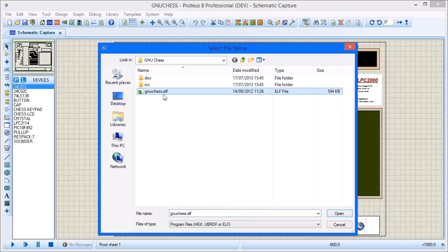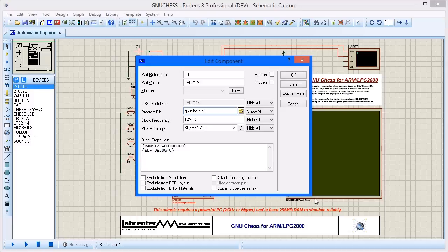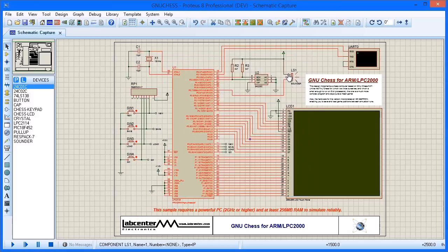However, for source level debugging, you should instead supply the debug files which contain the necessary variables and source code information. For most processor families, this is the ELF file, except for PIC processors where a COF file is normally produced by the compiler.